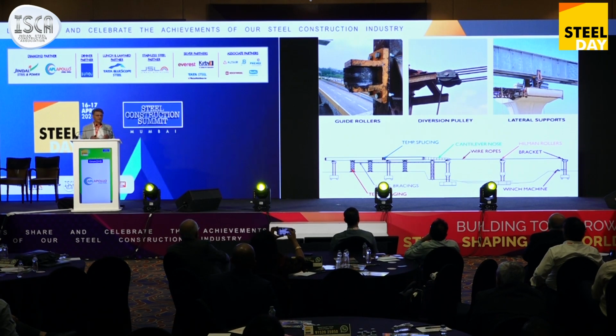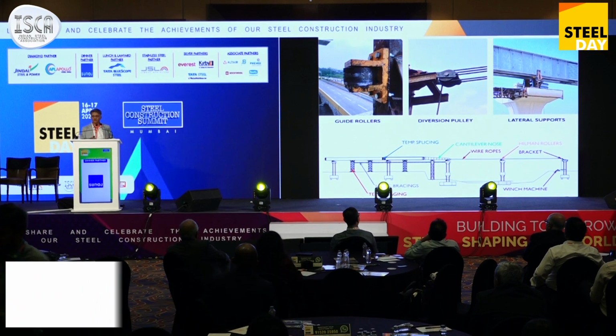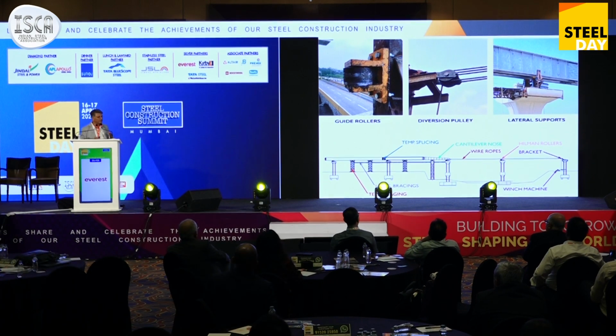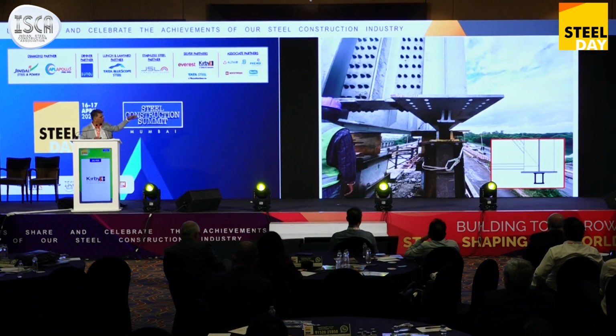It is a very special method where the river will not be disturbed, and no staging or support is required from the river portion. With this, we have moved the entire structure by connecting 2 of the spans to each other, using these Hillman rollers, over which our entire structure is rolling. While rolling, we have also used stay rollers so that the structure does not move away in the lateral direction.